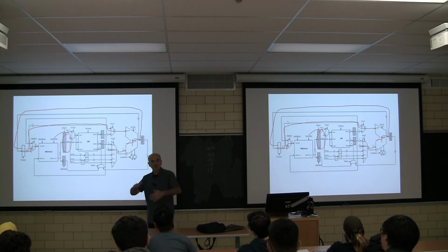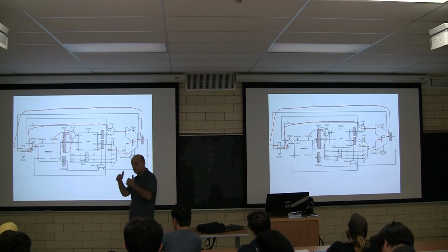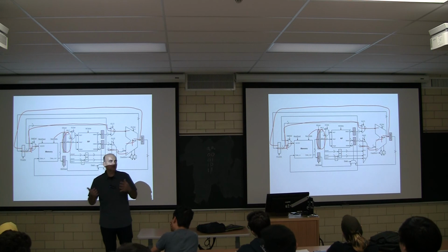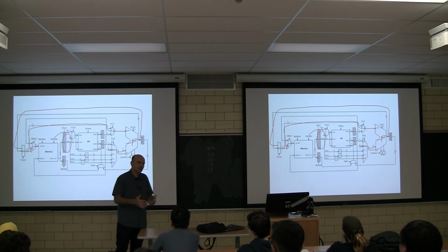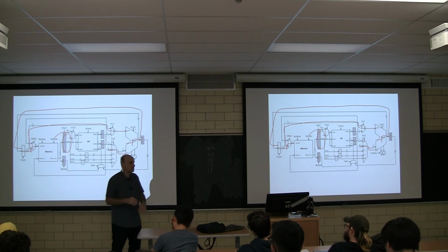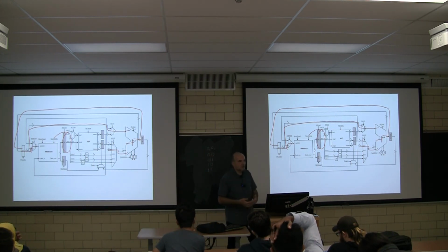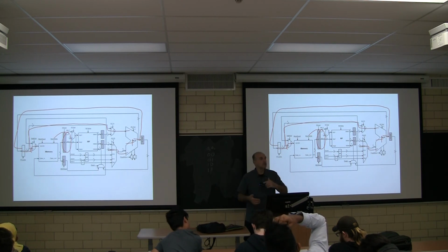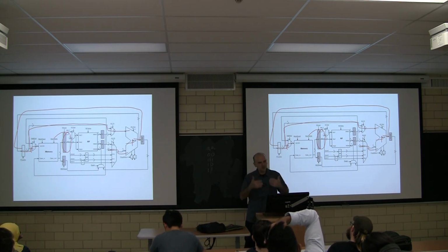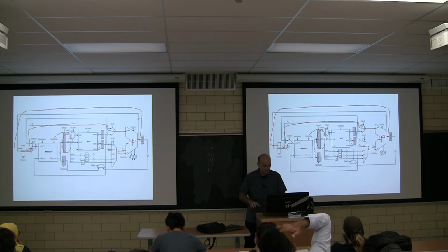Am I making sense? So before I showed you the instruction taking 6 cycles, where the PC plus 1 was the very last step. And now I'm going back to the optimization, which unfortunately I described early on. I said, instead of doing this in the very last cycle, we can do it in the very first cycle. Done. Second thing, what I did before, I wasn't doing speculation for round 1 or 2. I was waiting for these things to happen to make sure that I have to read it. I showed you early on that I can read it before as well. Sorry for confusing you like this. I hope this makes it clear now.